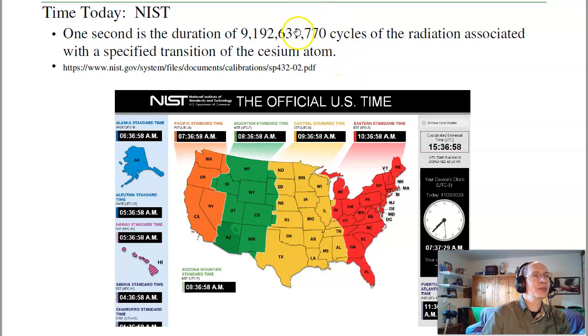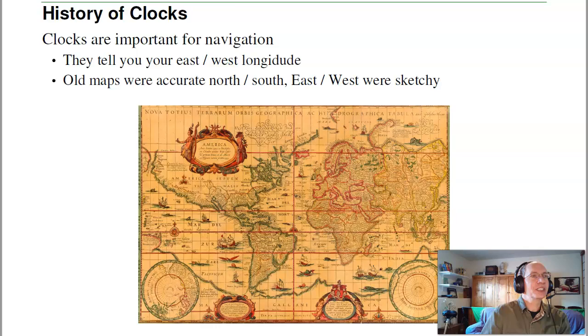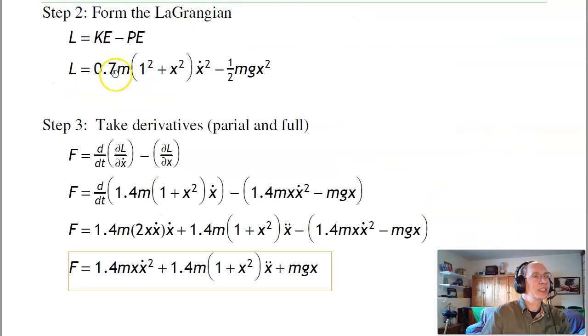So in summary, we've got the Lagrangian dynamics. What the Lagrangian dynamics do is if I can define the kinetic energy and potential energy of the system, I can tell you the dynamics of the system. And this works for both linear and nonlinear systems. You kind of see it's a little bit complicated, but it works. If I have a ball and beam system, or if I have a ball rolling in a parabolic bowl, the dynamics are fairly complicated. With the Lagrangian dynamics, I can get there. I don't know of any other method that'll get you this answer.